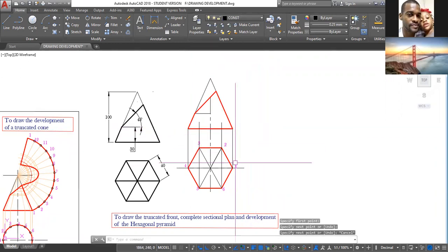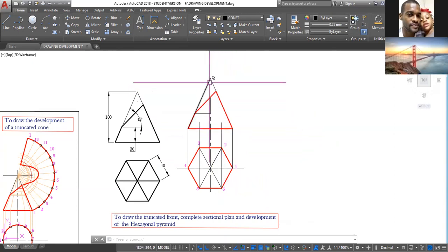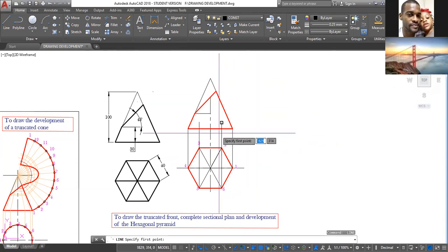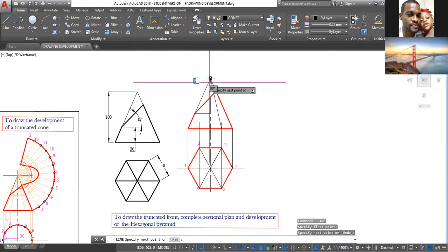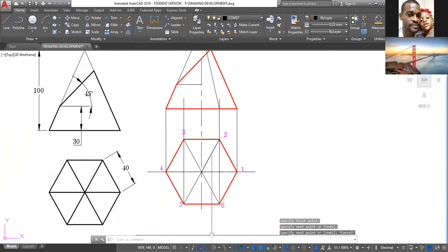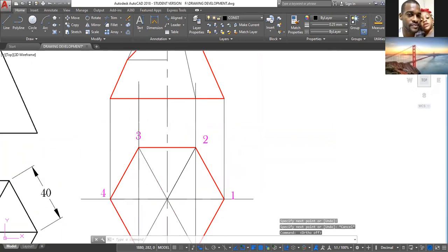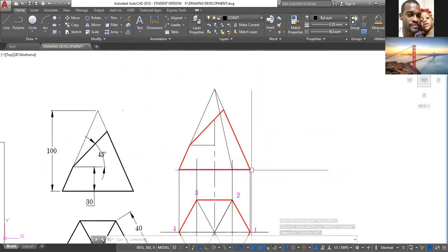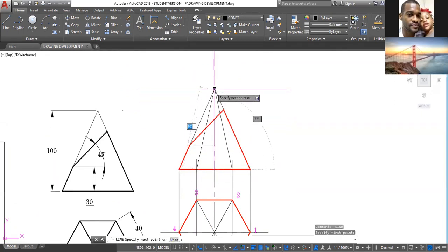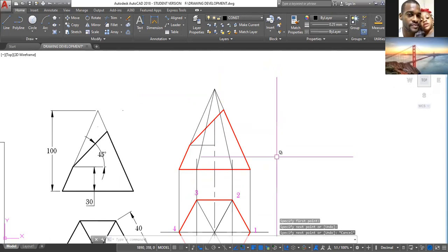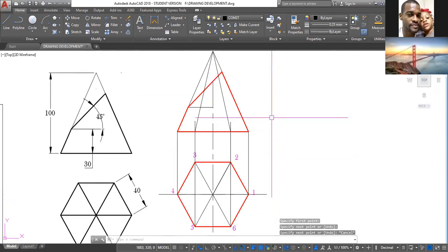Right, so we have all our sides. Now, we need to bring these sides to the apex, right? So we activate line L. So all the sides meet at the apex. So we have that. I need to deactivate the orthogonal mode. This allows me to draw lines easier at an angle. Space bar to reactivate line. Click here, escape.